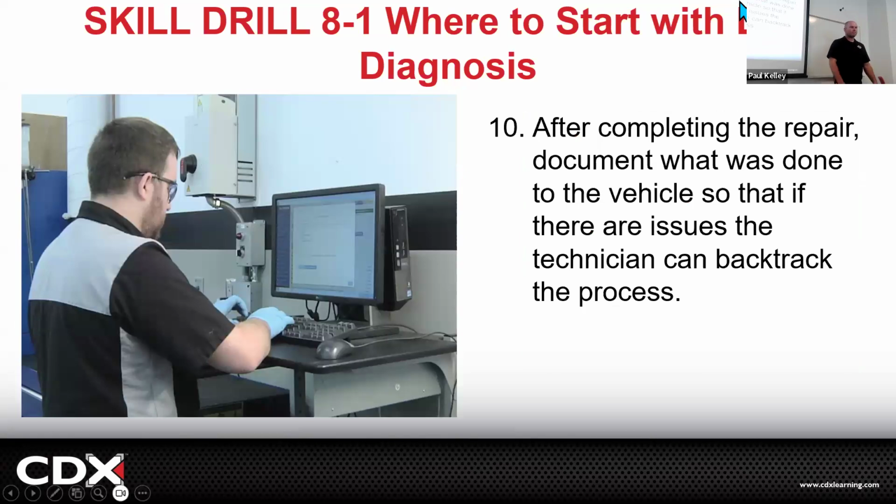You're going to do the repair, right? Maybe that last one was a head gasket. Cool. You go ahead, tear it down, and have the head checked by the machine shop. You put a head gasket in, you torque things to spec. How do you know how to actually do the repair and where do you get the specs? Yeah, again, service information is guiding you. You're never just doing it from your mind. You shouldn't be anyway. You'd be following the steps.